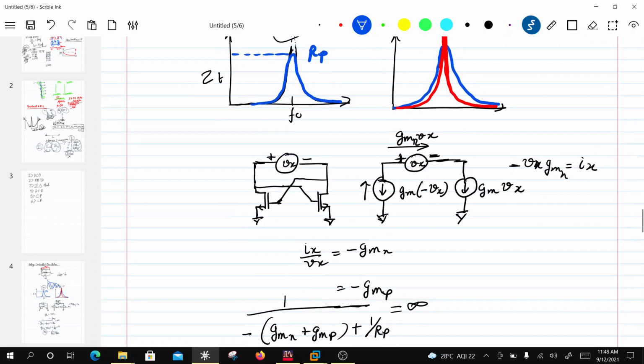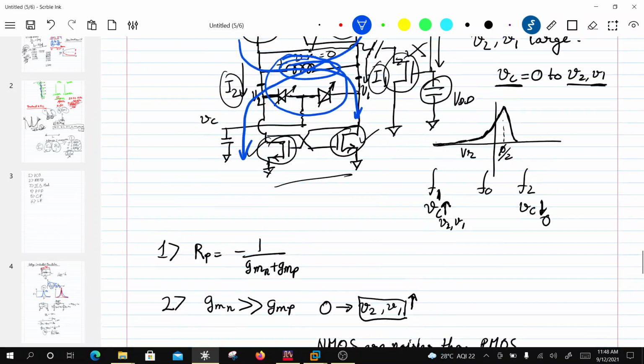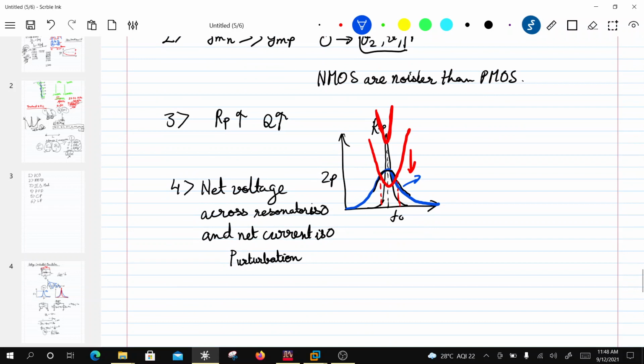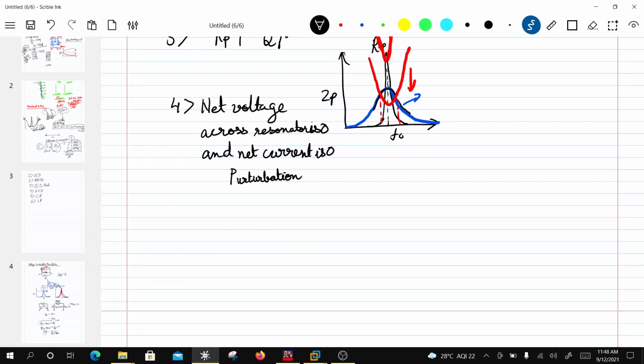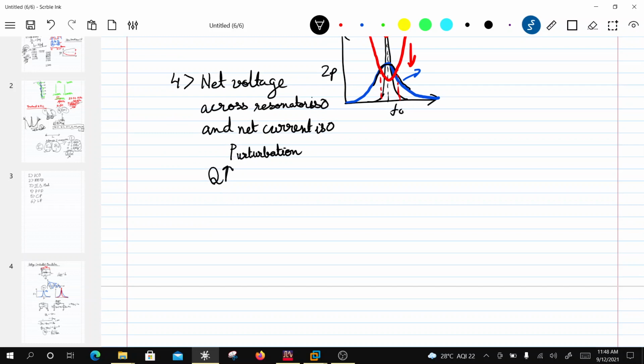So now this looks like garbage, the way my handwriting is not good, but I hope I captured the essence of what the Q of the circuit is going to do, right? So Q should be as large as possible. That means choose the tank circuit with... now the question is whether inductance is lossier or capacitance is lossier.